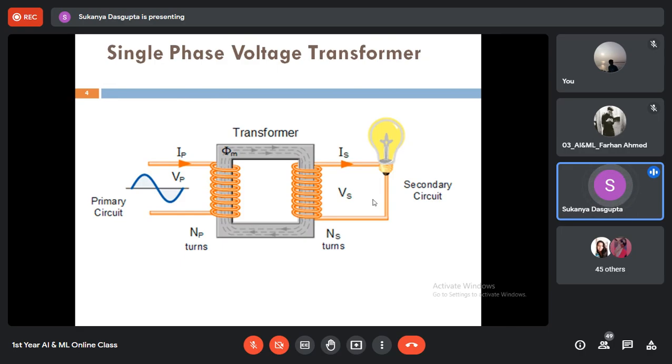DC can also be produced, but the transformer is basically an AC to AC device, and DC is possibly connected at the input side of the transformer till there is a rate of change of current. If current becomes steady or constant, there will be no rate of change of current, right? So there will be no production of EMFs. So a DC circuit is allowable if there is a rate of change of current.